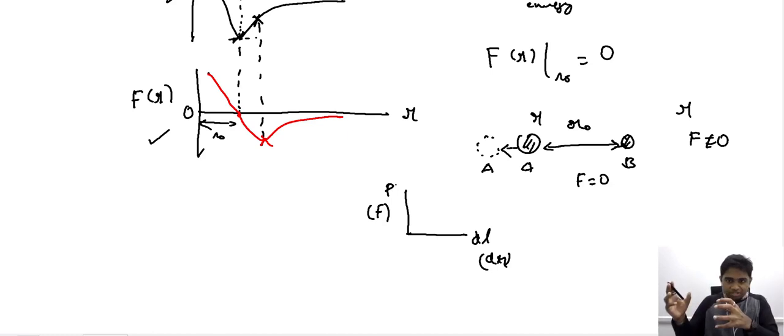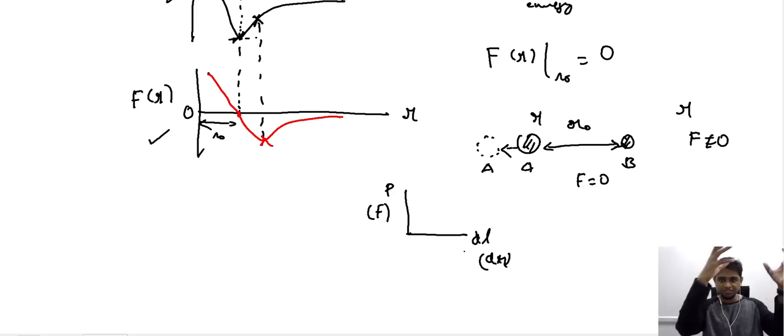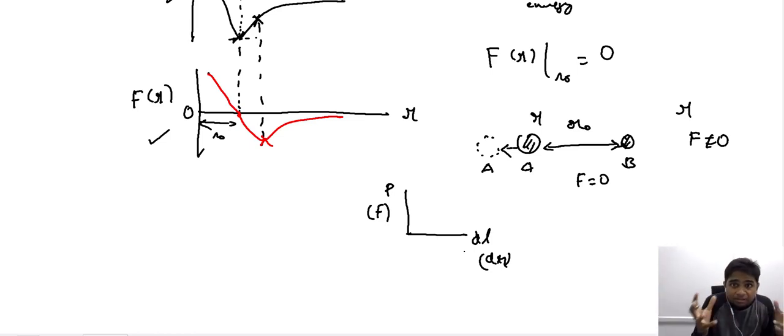When you consider this load elongation curve on the atomistic scale, what you end up having is the force versus interatomic distance curve. So on the macroscopic scale, it is load elongation. On the atomistic scale, it is the force versus the interatomic distance curve, and that is exactly what we have here. So the curve that we observe here is similar to the load elongation curve.